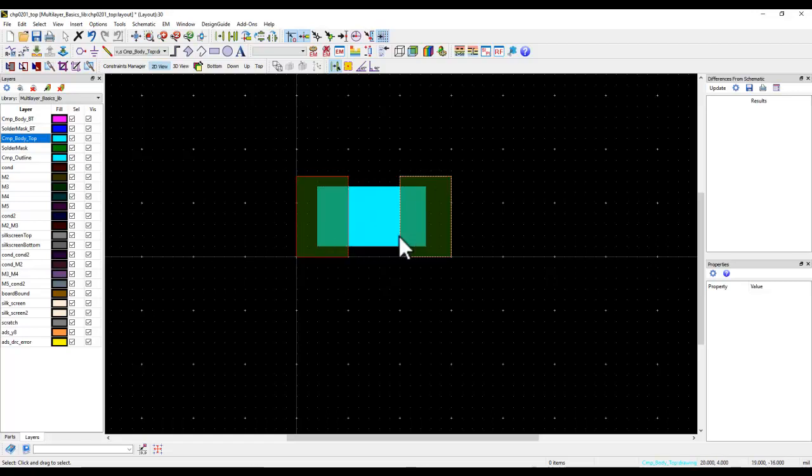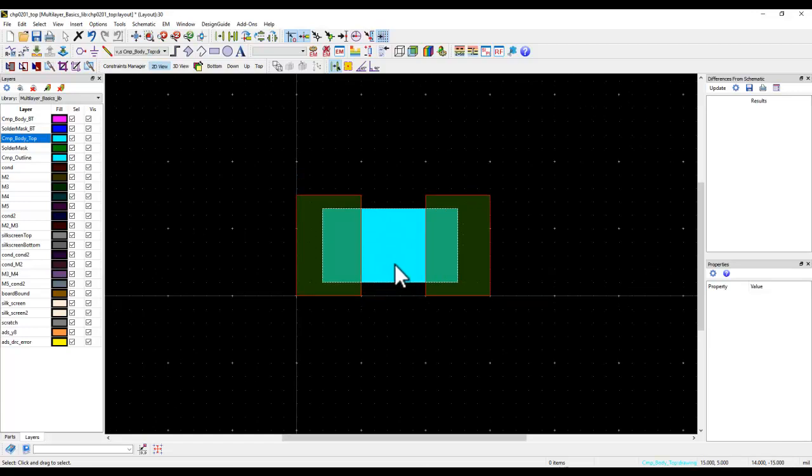Now to create a pin, the best way to do that, to make sure that your footprint doesn't give you LVS error at the end when you do your design qualification, the good idea is to make this entire pad as a location for port connectivity or the trace connectivity.